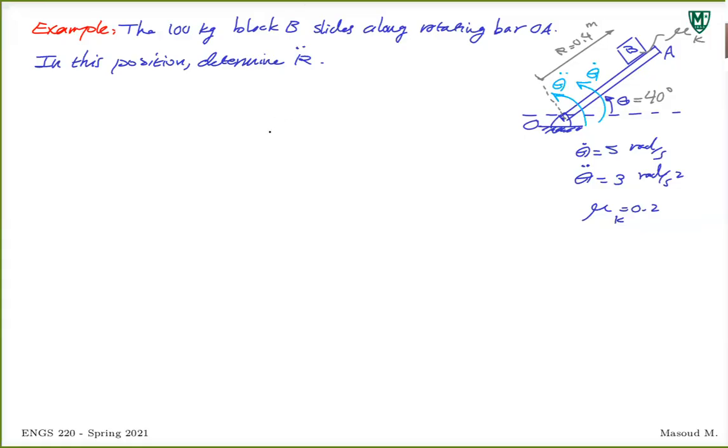All right. So same story. Start with whatever you want to draw the free body diagram for. Draw the free body diagram for that. Make sure you know your coordinate system. The positive direction, represent that coordinate system on your diagram so you know where everything is. And look into acceleration components. Form the equations by writing Newton's second law. So that's what I'm going to do.